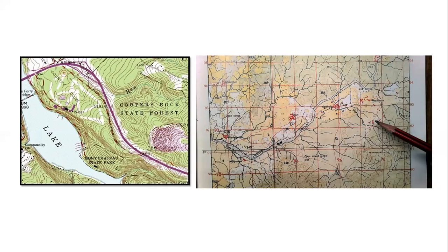I will collect samples based on my interest. For example, my objective is to find out the fertility status of one big area, some big district, for example Ayodhya. So I want to do fertility mapping for Ayodhya. Ayodhya is very big, so I will take a GPS and all my equipment like auger and sampling tools, and I will dig some profiles and collect samples. Where I collect a particular sample, I will note the geographical coordinates, the longitude and latitude, in the memory card of the GPS.